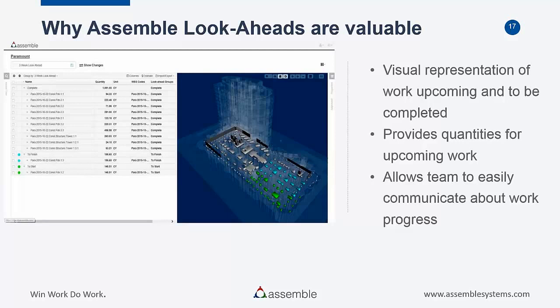And you get a little bit more than just that visual. You also get the quantities of that amount of work. So for example, the concrete guy says, okay, great, I see how many foundations there are, and really quickly he can get the count of them. Okay, how many cubic yards of concrete am I going to need to get delivered over the next 3 weeks? Well, 196 yards is supposed to be finished this week. So, okay, that gives me an idea how much concrete I'm going to need.